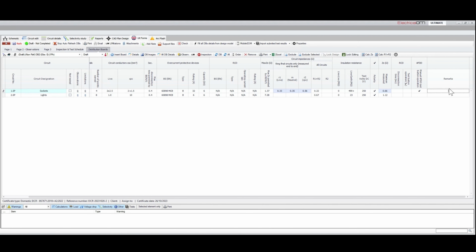So with that USB socket, for example, on the socket circuit, obviously there's a path line to neutral through whatever it is in there that makes the USB magic operate. However, there isn't a real path back through to earth. So the filtering on that, the earth filters within that USB socket were holding up strong enough for the duration of the IR test for that not to be a problem.